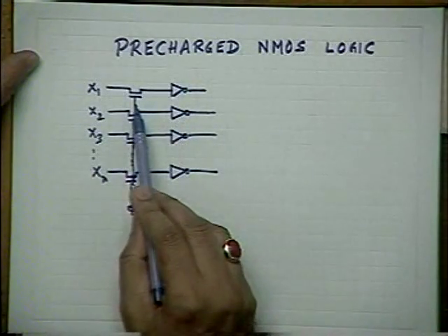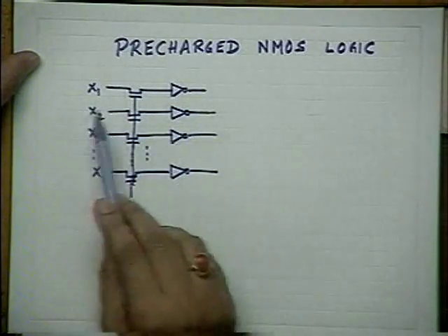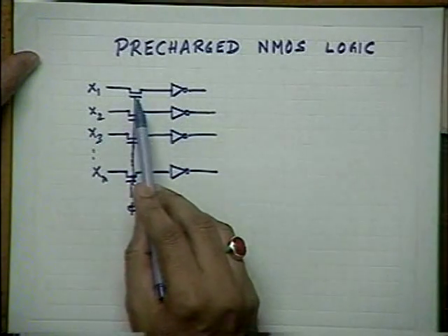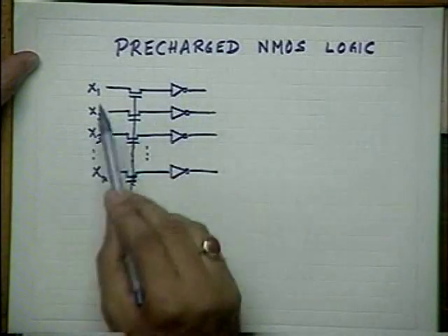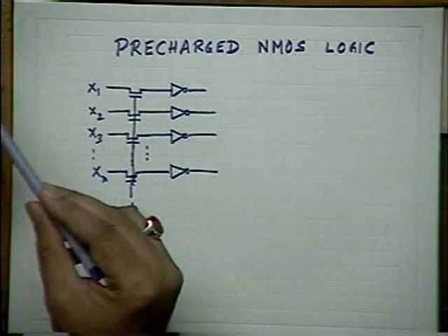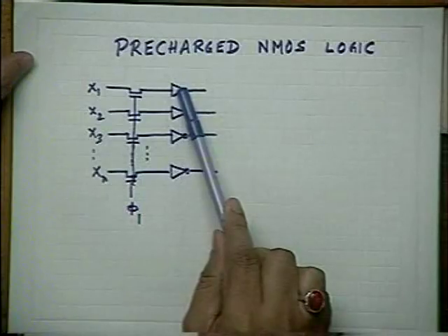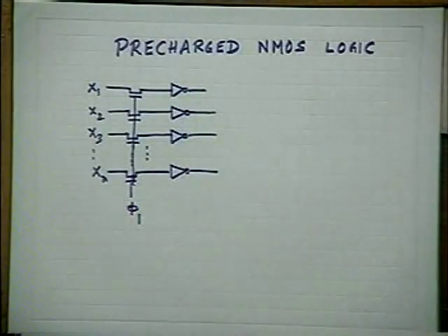Here we assume that there is a steering gate at each shift register channel. There is a steering gate and an inverter. But as we have seen, this may not be a traditional inverter; we can realize it using switches also in the ratioless design. In the ratio design, these are ordinary inverters, whereas in ratioless design, they look like inverters, but they actually behave as switches, so naturally there is no need of maintaining a ratio. This is what I can call an n-bit half register.